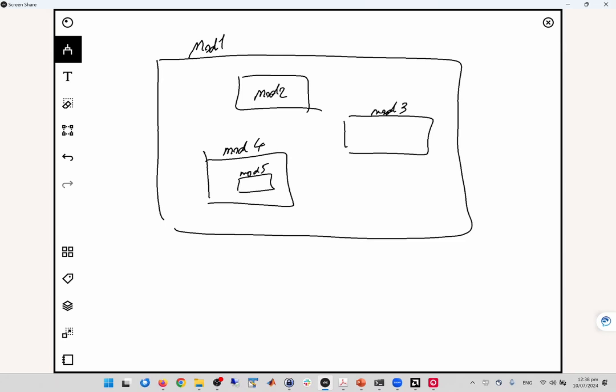It means that the elements in module 2 should never come out and be optimized with other components and gates of the other modules. If you make an AND gate here and keep the hierarchy, the AND gate should stay as it is. Of course, inside module 2, if you have many different gates, they can be optimized, unless you say that the AND gates or other components you instantiated should not be merged with anything else.